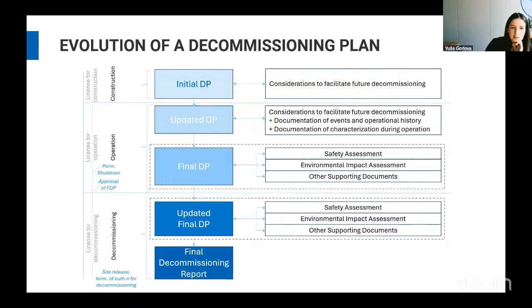It is still possible that the decommissioning plan might need to be updated when you really start to decontaminate and dismantle the elements, systems, structures and components of the facility. Sometimes it contains some surprises. For example, when you start to actually drill and dismantle something, sometimes the licensee realizes that there are some other issues that were hidden from the eyes or from the documents, sometimes with materials, sometimes with some deeper activation in the structures where it wasn't expected, or something else.